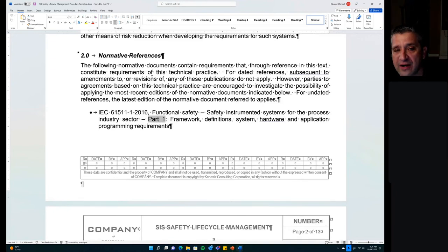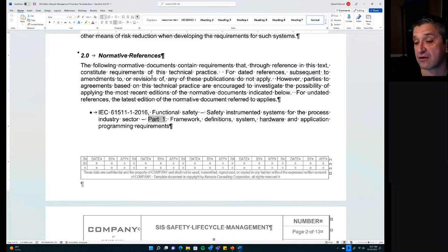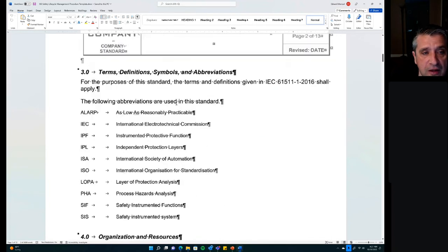So maybe your organization has some machine tooling, you're going to want to include the machine tool standard. Perhaps your organization does a lot of boilers, you might want to incorporate NFPA 85 by reference for the boiler work. Perhaps you have higher level corporate standards, but you want to write a standard for your specific site. You might want to include those references to your higher level corporate standards. That's what you're going to want to do when you're editing clause 2, the normative references.